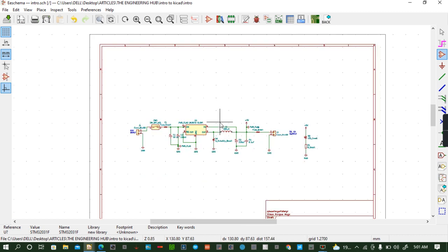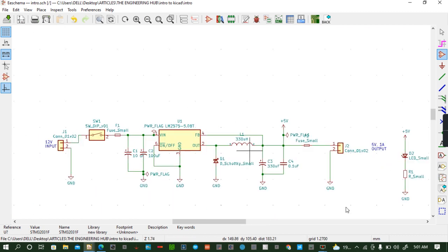And I think for today we have learned enough. We have learned how to annotate a schematic. We have learned how to perform electrical rule check. We have learned how to assign PCB footprints to schematic symbols. And we have learned the big animal in the house, which is how to design your own footprint when you are not happy with the footprints in the library.